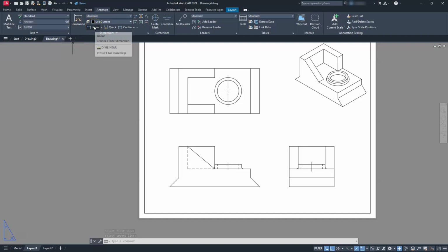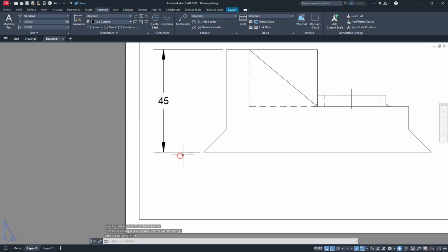They're just linear dimensions. You've seen me do this in 2D, but all I'm doing is selecting the two endpoints that I want. The same principle applies. So always remember that if you want that dimension to be here to the bottom, make that the last point you select.